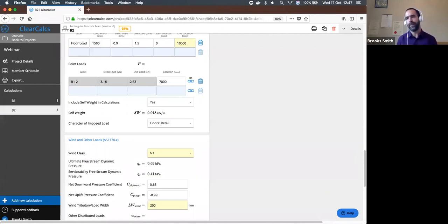Yes, the beta 3 factor has been entirely removed. All of the beta factors have been removed. There's no beta 1, beta 2, or beta 3. It's just been entirely replaced by KV. So you're not specifically accounting for high shear near the supports anymore.